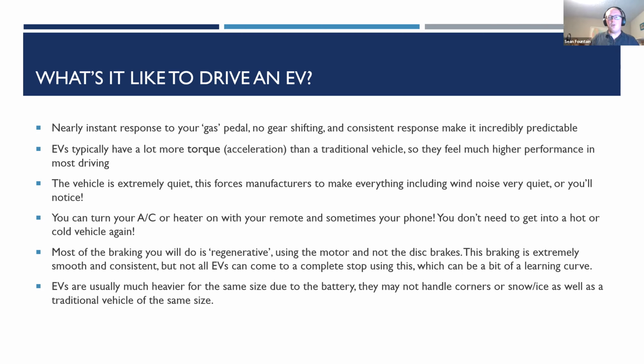And a lot of drivers, they found, did not like that initially. So they would leave it in the regular drive, which is the normal driver preference, where it only very lightly slows your vehicle down with regenerative braking. And then if you press the brake pedal, and it depends on the car, for the first like 10 or 20% of the pedal, it feels a little different, and that's on purpose, so you know. It's just telling the motor to brake harder. So in Chevy vehicles, that's how they did it. I believe the Ford Focus and stuff is also the same.